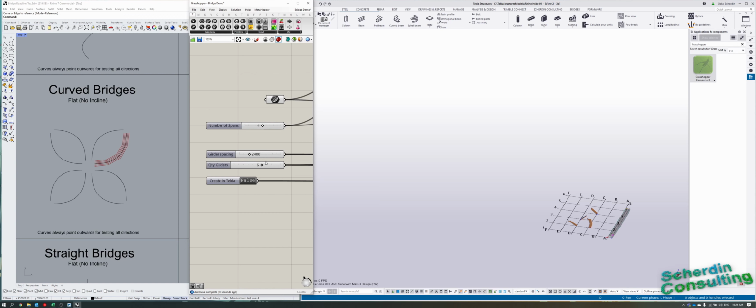We can pick another road line, but if I just press this button here, create in Tekla, we'll just have to wait a bit, and now what it's going to do, it's going to take each one of those lines in space, place a girder and push it with different settings, so different skew angles. It can have different void settings depending on the lengths, everything that I showed you just before. It's going to do automatically for me. But at the end, I end up with a bunch of components or plugins in Tekla that I can manually adjust instead of having to rerun the big script again.